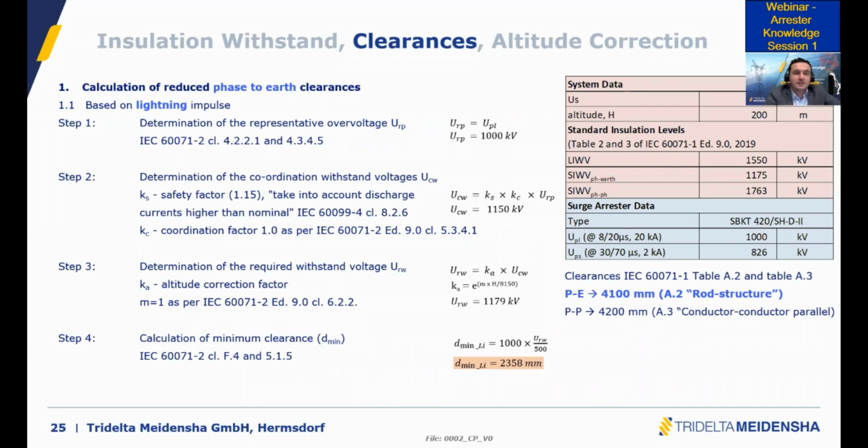Okay, this is an anonymous question, the next one after the previous question. If you have a 1,500 kV BIL and you pick a protection level of 1,425, for instance, I understand that this is nonsense because the possible overvoltage will be close to the BIL. Yes, you're right. But what is nonsense here is this protection level for such a BIL.